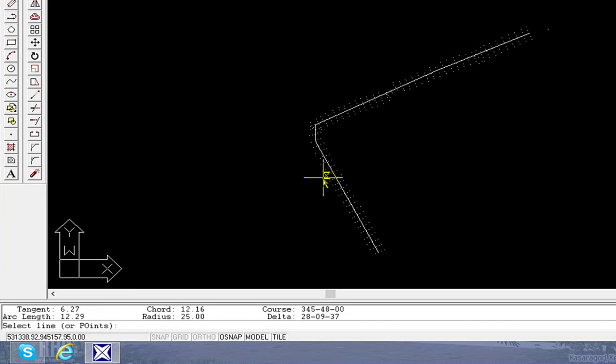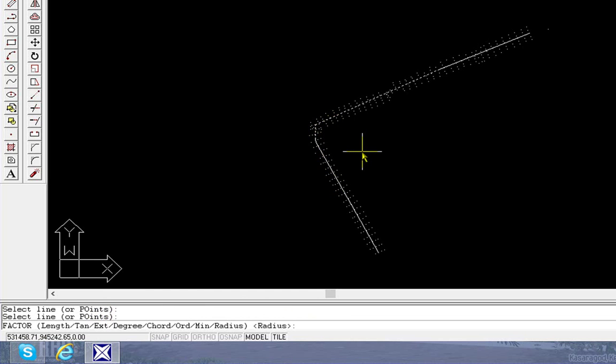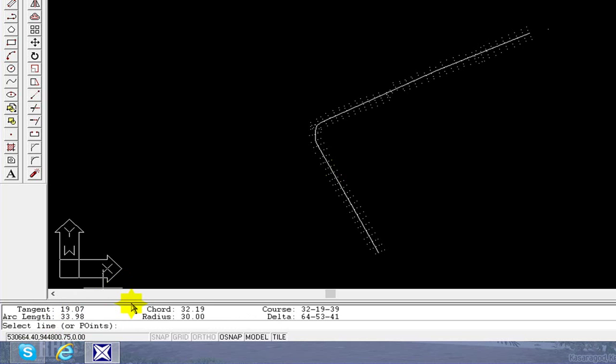The curve is represented by 25 radius, and for the second tangent, click on this and click on this one, and again press enter on your keyboard, and it says on the command enter the radius, and you can enter the radius 13 and press enter. This one, or curves indicates by this,